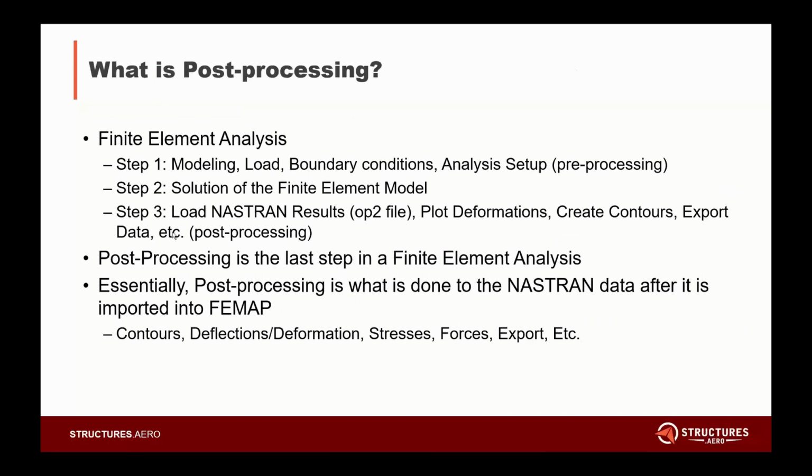So I'm just going to go ahead and jump right into it. We're talking about post-processing today. So I figured it was worthwhile to talk about what exactly is post-processing. Well, let's start with what the finite element analysis steps are. With step one, you typically start with modeling. You put in loads and boundary conditions, and you set up what kind of analysis you're going to be running. You can run static analysis, modal analysis, nonlinear. That all happens in step one, which is known as the pre-processing.